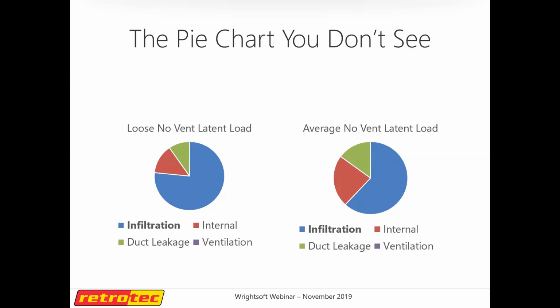Not really. I mean, you can have a humidification load, but you still calculate that as sensible. So for those of you who don't know, because I'm really used to talking to HVAC guys, latent is the moisture removal needs of the building, the latent heat. They call it that because of the sensible heat, and I don't even know if this is true, but it's a good way of thinking of it. The sensible heat is the one that makes sense.